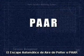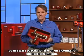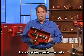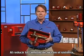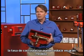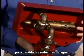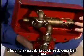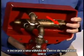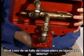The Potter Automatic Air Release, or PAR, is used to vent the air in a wet sprinkler system. Corrosion is most pronounced at the air and water interface line in a sprinkler system. By reducing the amount of air in the system, corrosion rates can be greatly reduced. The PAR has a water retention pan to hold small amounts of water that may be discharged during the venting process, and incorporates a unique safety shutoff valve that will stop the flow of water should the vent fail in the open position.